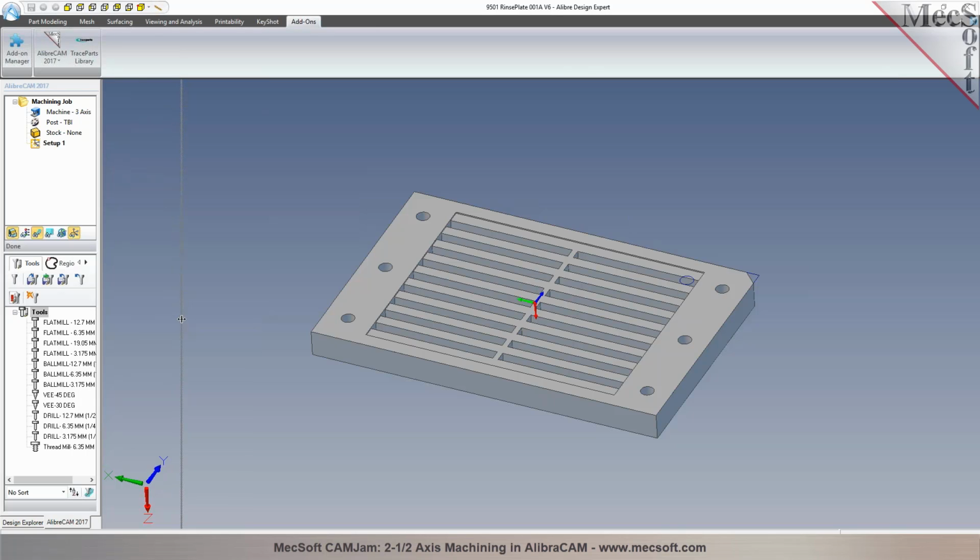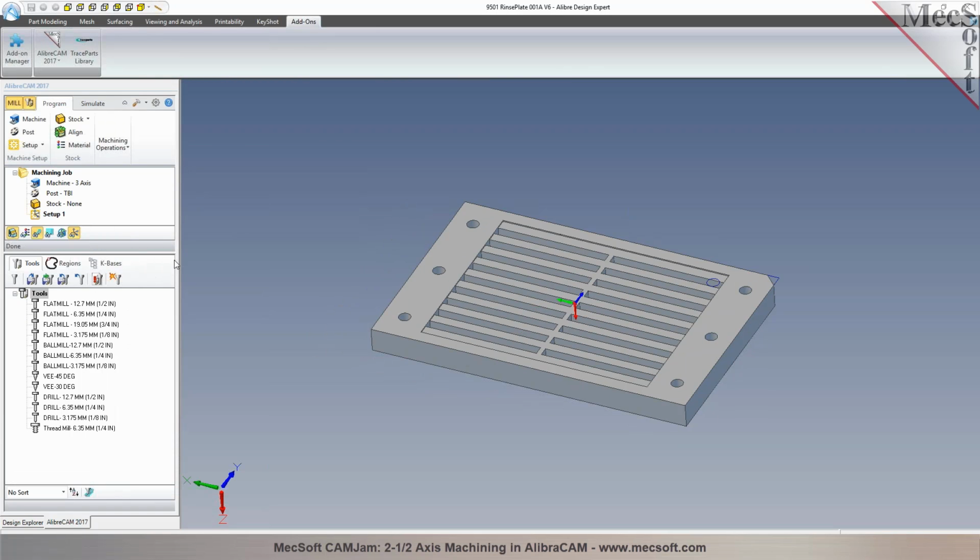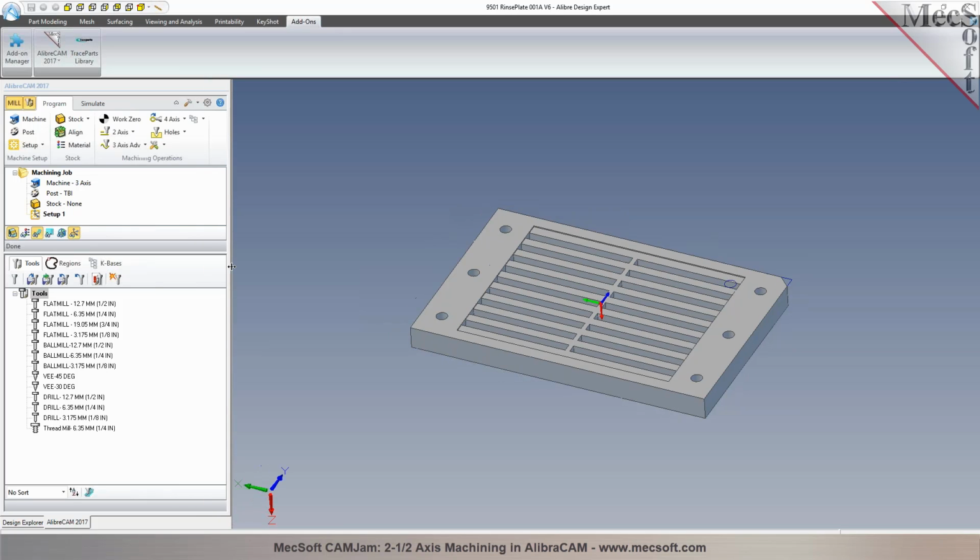Okay. So once you have the machining CAM interface browser loaded, you can resize this in here by just dragging it over, so you can actually view all of the contents in here. So you have all of these controls that'll allow you to change, update the UI the way you want it. It'll also allow you to resize the viewport. So once you save this information, it'll automatically maintain the width of the user interface, the browser that you set, automatically for you.